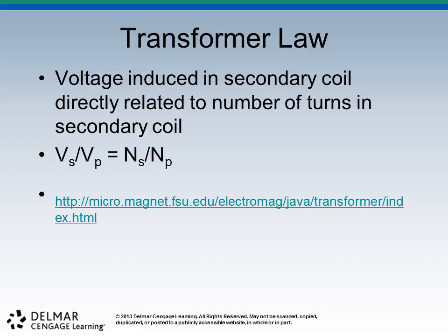There is a link here that I'd like for everybody to take a second to go look at. It displays how the transformers operate, and what you can do is manipulate the number of coils on the secondary and primary side, and take a look at how transformers change the output voltage based upon what the input is, the number of coils are. That, folks, whenever you manipulate those turns, that's exactly what you're doing when you change your kV from 40 to 50 or to 60 or to 70.